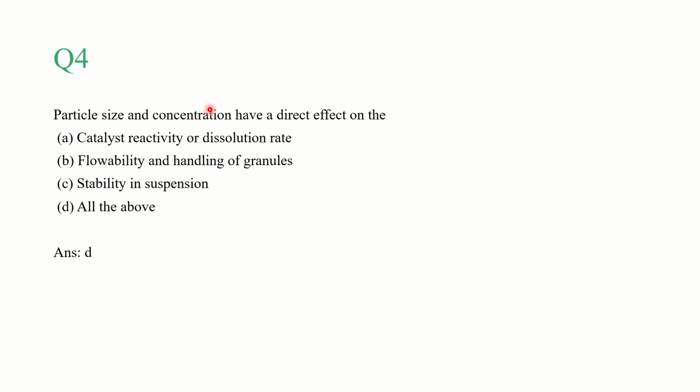For example, consider the particles before breakage or grinding, directly from the mining sites. They would be very large, and it would be difficult to carry out tests or the process with those particles, rather than with particles that are broken down. So the handling and the flowability were much improved with the particle size, and the similar thing applies with the concentration effect, and also stability in suspension. We all know that particle size and concentration matter where you are adding some solute or solvent, wherein the suspension medium in turn has a stability, right? That stability would be very much governed by the particle size and the concentration.